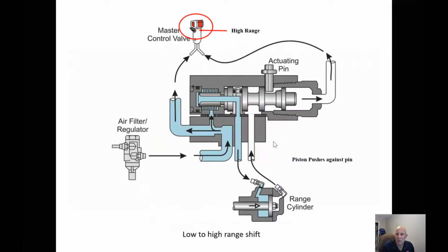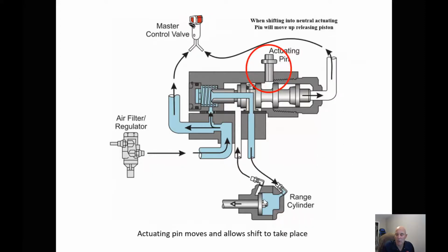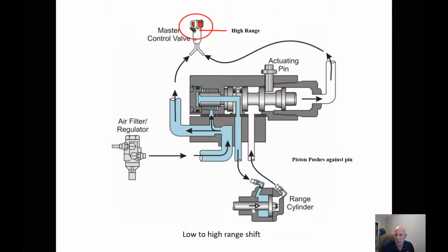Same thing as if we're in this position here and we have air leaking inside our transmission out of our breather all the time, but we go to this position here and it's not leaking. It's the O-ring that's on the shaft for the high-low range that's leaking. It doesn't leak here because air pressure can't get by this O-ring, so we get no leaks, but in this position it can. So understanding how the system's set up is going to help you troubleshoot.